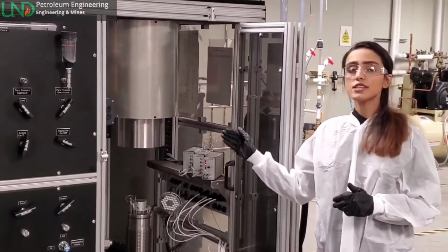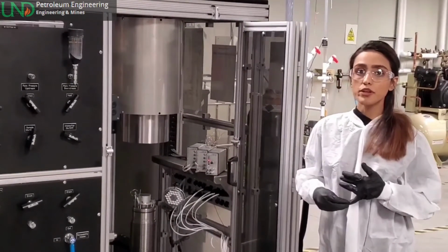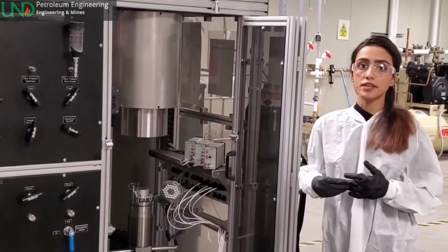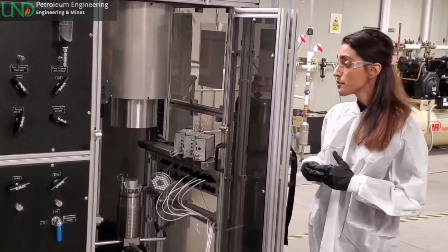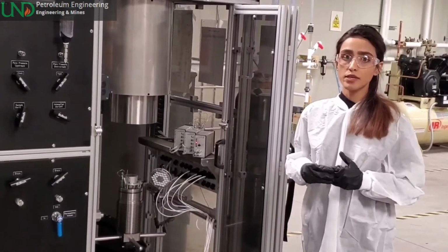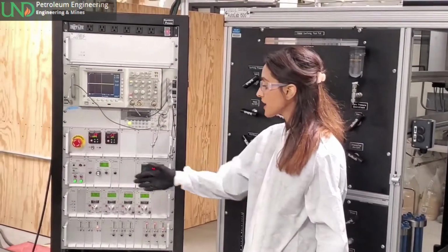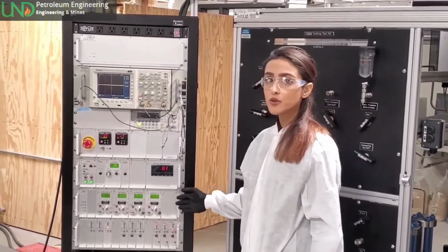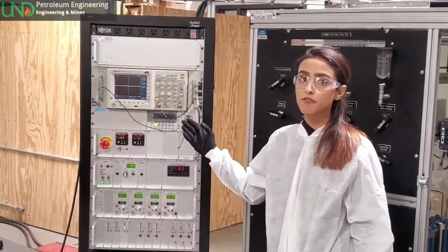which uses the 4 pressure intensifiers to generate confining pressure, core pressure in upstream and downstream, and differential stresses. Also, it should be mentioned that the core pressure can go up to 20,000 psi. Second one is the electronic control panel, with which you can generate and control pressure, or you can change the temperature and also observe different wave velocities.